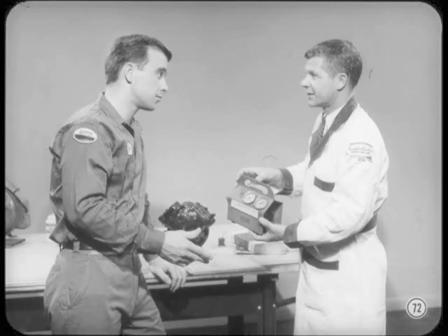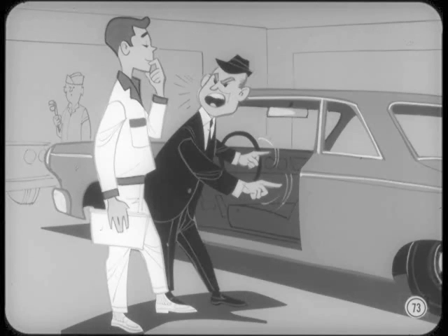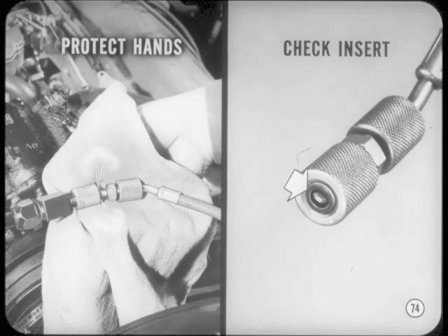Okay, but what if the pressures are normal, after adding refrigerant, for instance? Where the pressures read normal, the system's probably working at full capacity. But to be sure, you'll have to run a system performance test, especially if the weather's hot and humid. You see, where the humidity's high outside, the air in the car will not get as cool as in low humidity weather. However, it usually is reasonably comfortable in the car because the air conditioner lowers the humidity. Explain this to the customer and use the performance test to demonstrate that the system is working at full capacity.